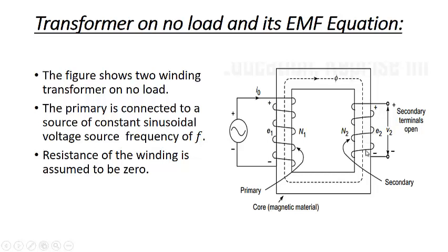Similarly, for this case, you can see that the flux direction is downwards. Let's assume we connect some load and see what will be the direction of the current. When we do so, the flux direction is downwards. I will do the same thing again. We'll curl the fingers around these turns, pointing the thumb in the direction of the flux produced by this winding, but this will produce flux upwards to cancel out this flux. So you will see that the current direction in this case will be like this, this direction, this direction, this direction.